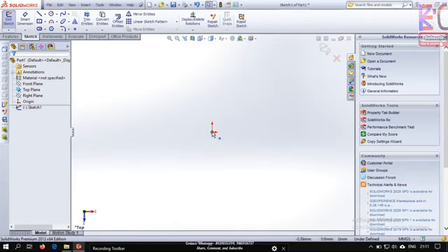Since the computer also knows that we can't always land exactly on the point, it gave us one more important thing, that is the star mark. As you can see, there's a star with an arrow shown in the center of your display. That shows that you are at the point or the center. Now you have to understand this is showing center, but down below it is showing minus 0.54 mm. That doesn't make any problem. That means you are selecting the origin. If it's a star, it is showing that you are at origin.